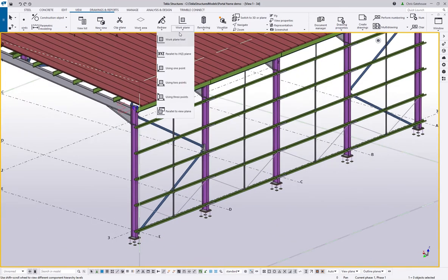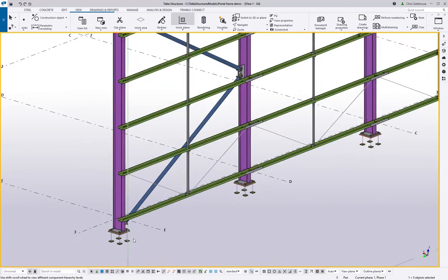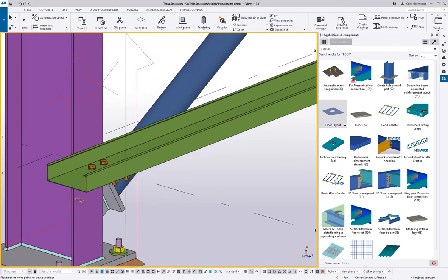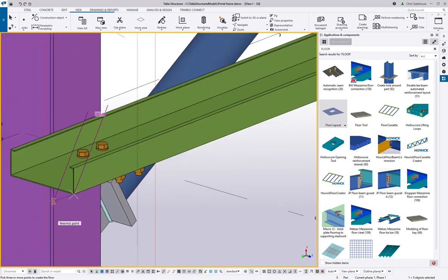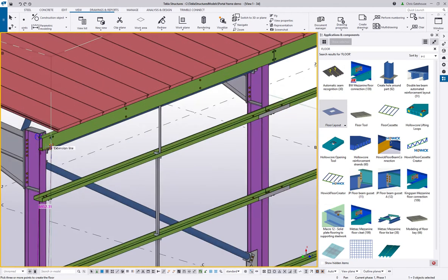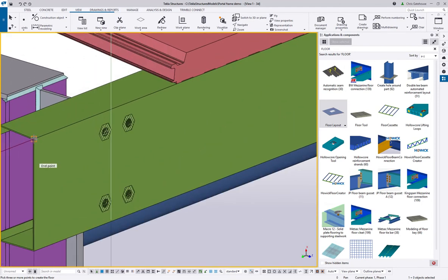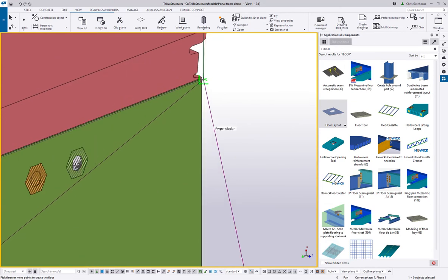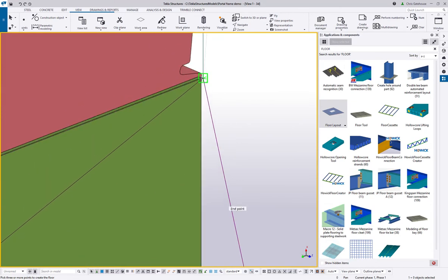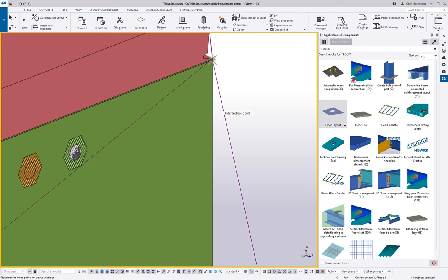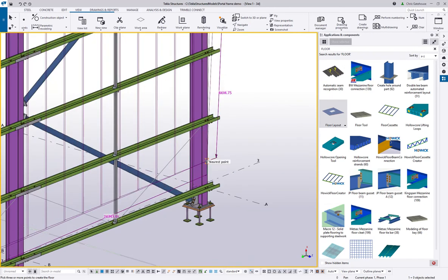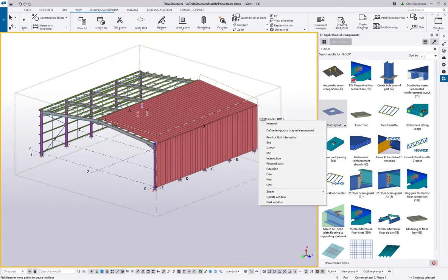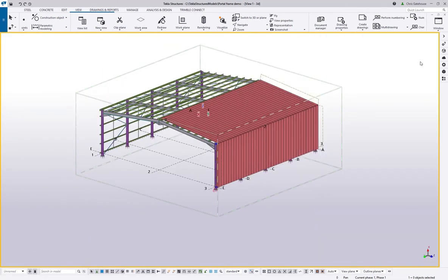So if I change my work plane to face the column, we can do the elevation. And then I'll show you a couple of neat tricks before I wrap up. So again, we want vertical sheets. Then we pick the final two corners to define the area, like so. And then down at the bottom of that rail, middle button to finish, and then we've got our elevation.